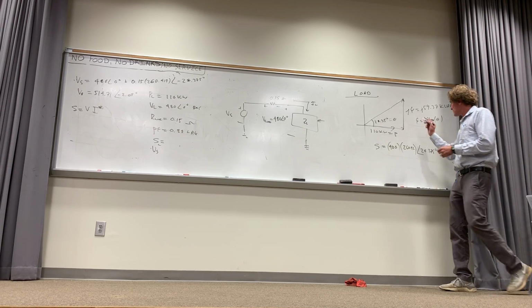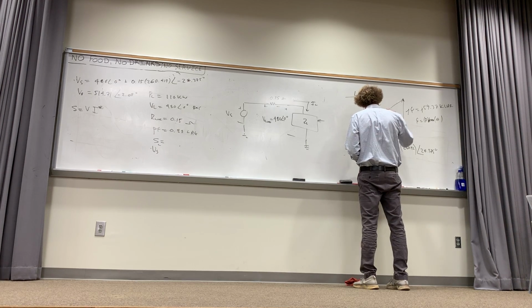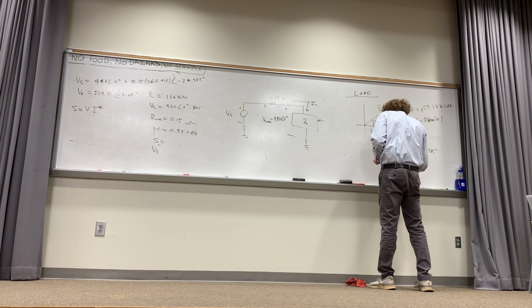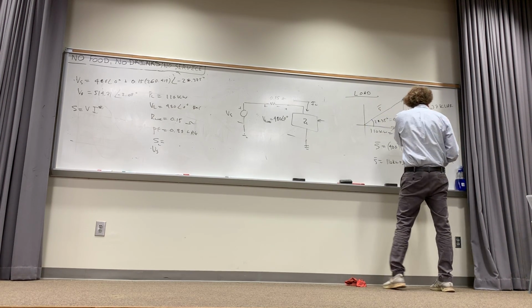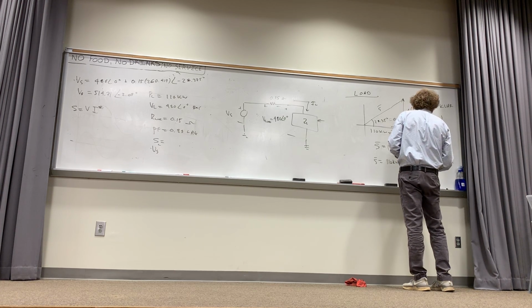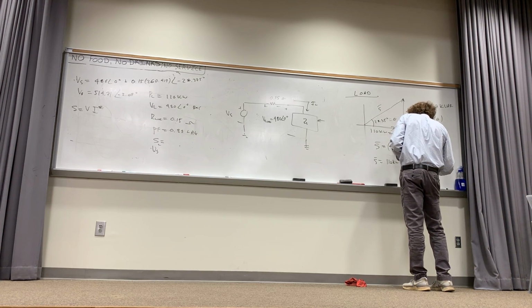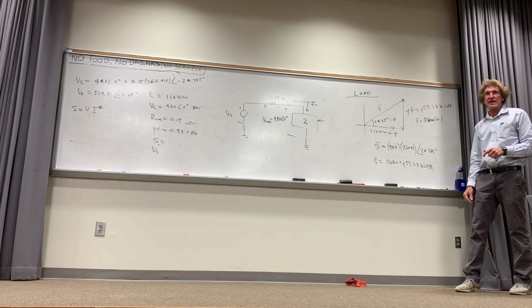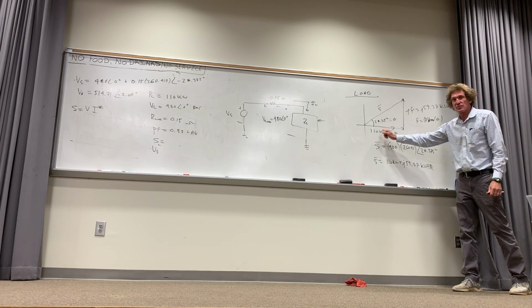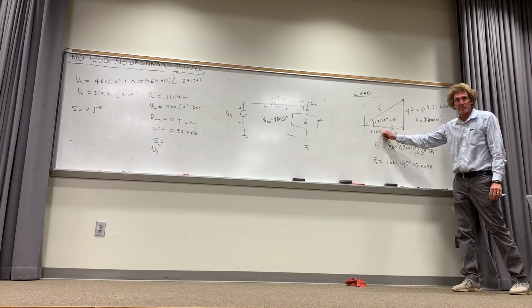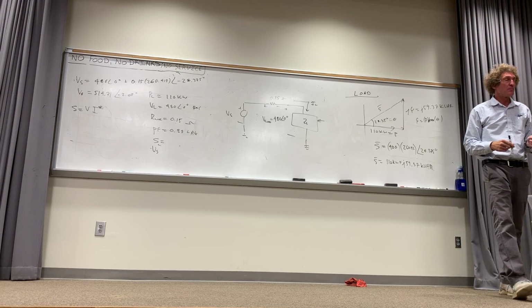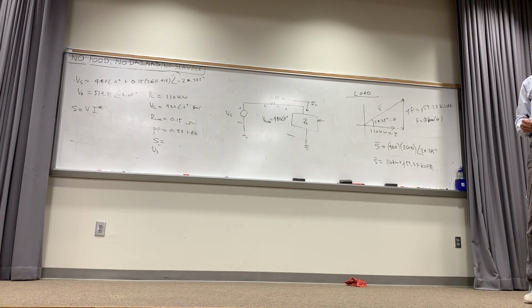It's also equal to, you're going to see this is S right here on the diagonal. S is also just equal to this P, which is 110 kW, plus jQ, which is 59.37 kVAR. The k is just 10 to the third. VAR is volt amp reactive. It's indicating that this is reactive, this is real. Watts are dissipated. You never get this power back. We get this power back, you could say. And the complex power here, that S is the sum of the two, and its units are kVA. There's no R, just volt amp. All right? That's all it is.